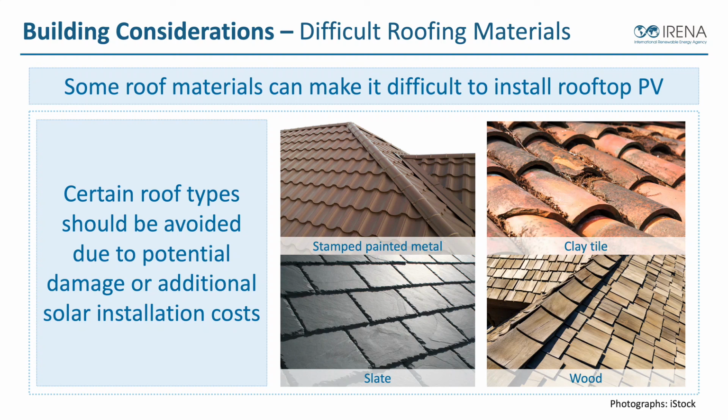Now, all of these roofs, if we did solar as new construction and used these types of roofs, integrating solar in the new construction process, these are a little bit easier to deal with. In a retrofit, these make for difficult or costly situations. A lot of times we've advised to remove that roof. So let's say we want to put the solar where the clay tile is. Maybe we remove all the clay tile and we put a different type of roof underneath it that's easier for us to waterproof. So there's ways around it, but these add costs compared to the other types that we just looked at.